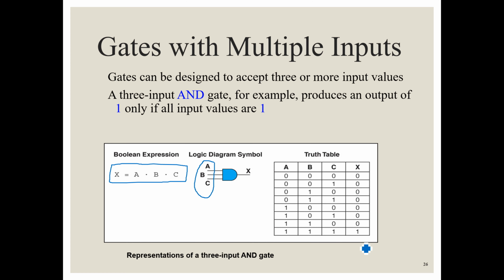As per the working condition of the AND gate, if all the input signals are 1s, the output is going to be 1, or else it will be 0. Only in the last state are all the inputs 1: A, B, C are 1. So that's why your output is going to be 1. In all other states it will be 0. This is regarding the 3-input AND gate.